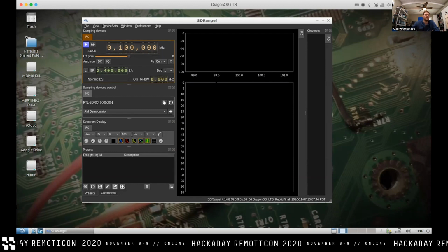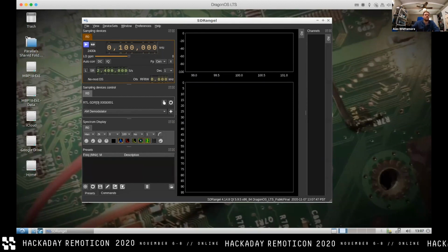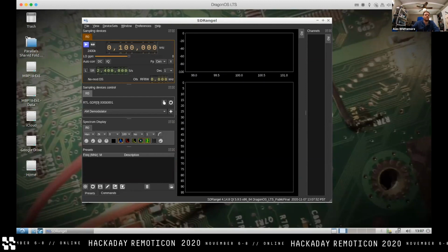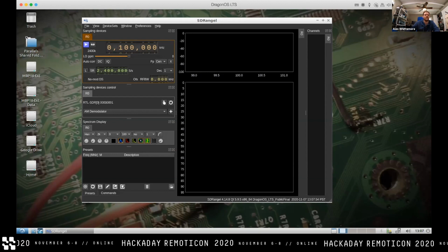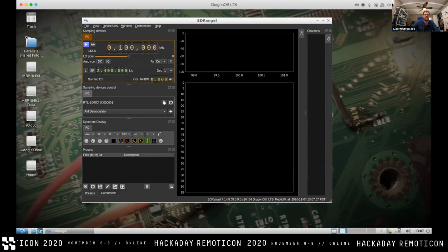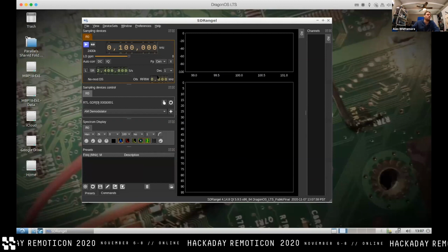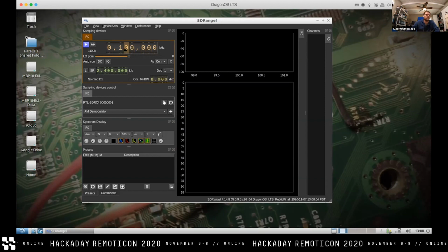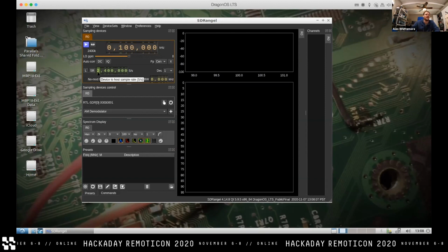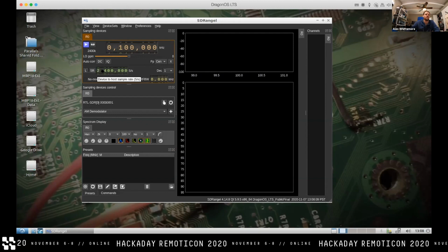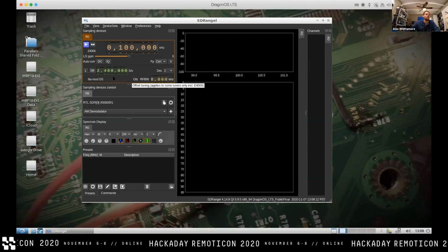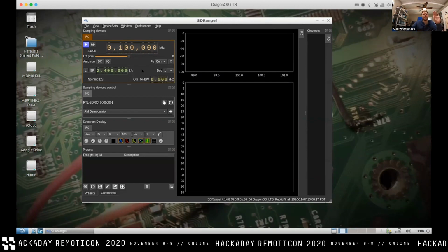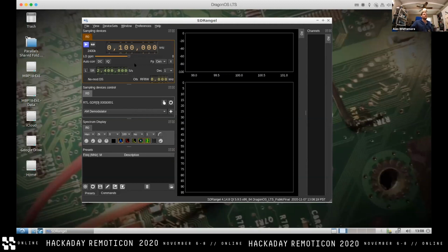Recall that this is not operating as a swept spectrum analyzer. This doesn't have anything like that. So the sample rate affects the maximum bandwidth span, where previously I was setting that span to 100 megahertz and setting the center frequency at 50 megahertz over on the RSA. Right now, I've set the center frequency at 100 megahertz. The span is set by the sample rate. So we've just got 2.4 mega samples a second, which is a 2.4 megahertz bandwidth. It's I and Q, so Nyquist is satisfied.